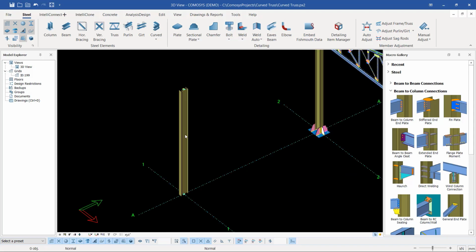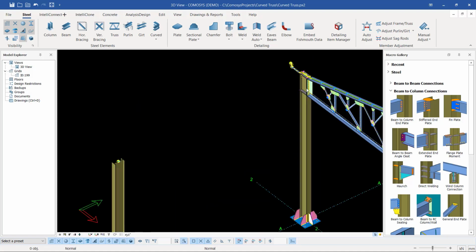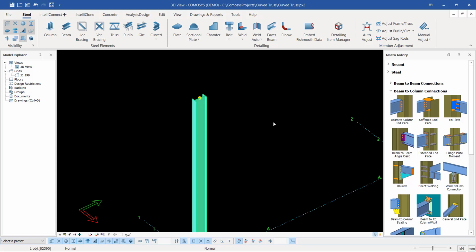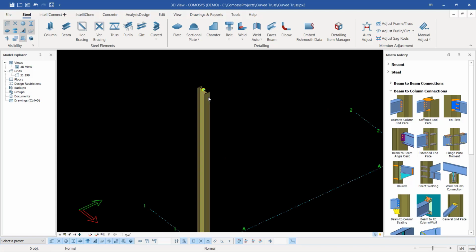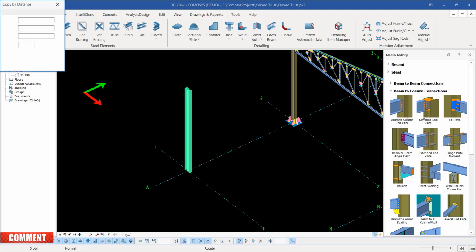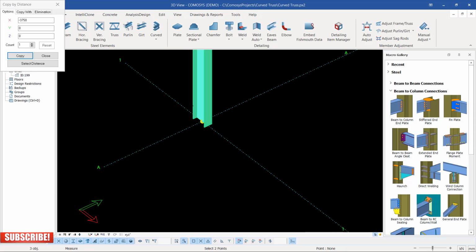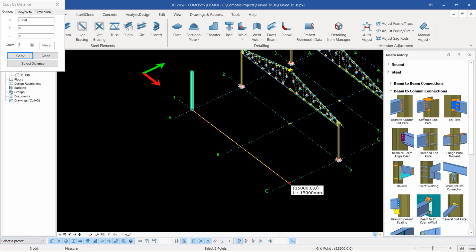So it is in place, but the orientation of this particular member, it's not the same as this. So the connection or placement of our portal rafter will be harder. So let me just select on it, then press Ctrl Q so that the orientation becomes in a better position. So I'll select that once again, right click and come to spatial copy and pick on linear. So I'll scroll closer to that joint, then span all the way to this far end here. So I'll snap at a distance of 15 here, and I'll snap it on that spot.